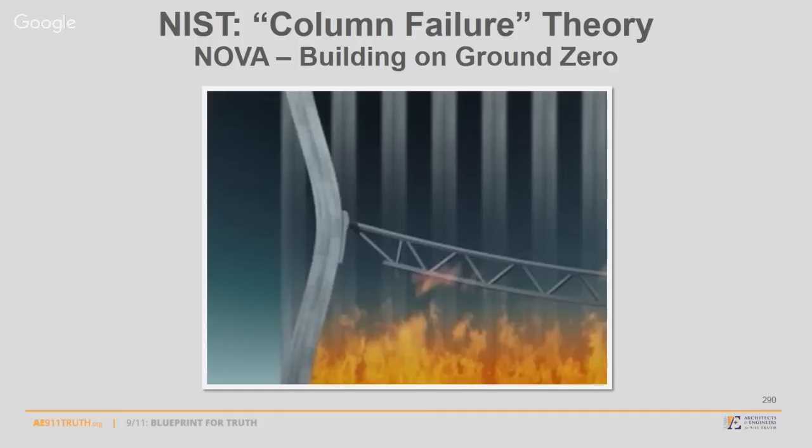Their theory, basically, is that we have outrageous, raging fires, and underneath, lightweight steel trusses, which caused them to bend, which caused, in their theory, the perimeter columns to bend inward. That caused the overall buckling of these columns, allowing the heavier section, in the case of the North Tower 15 stories above, to then collapse onto the story below and drive the building all the way down to the ground and destroy itself. We're going to be evaluating that theory today.